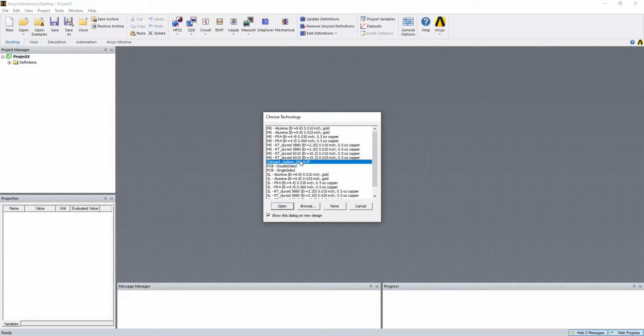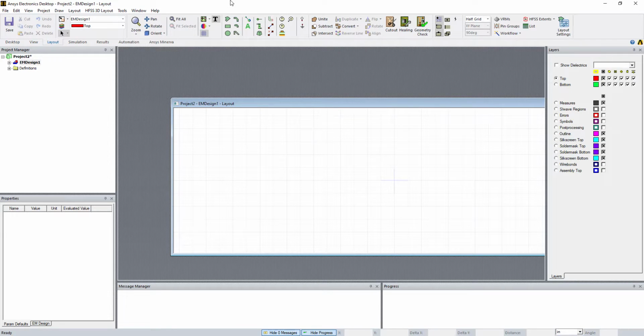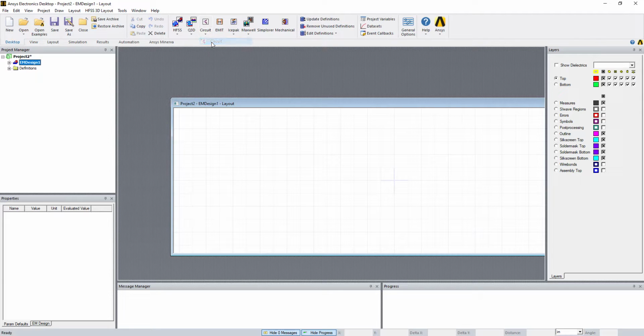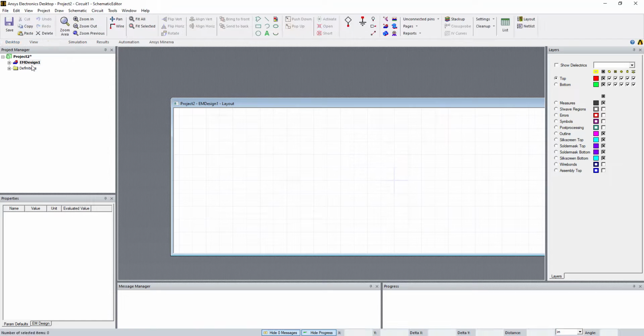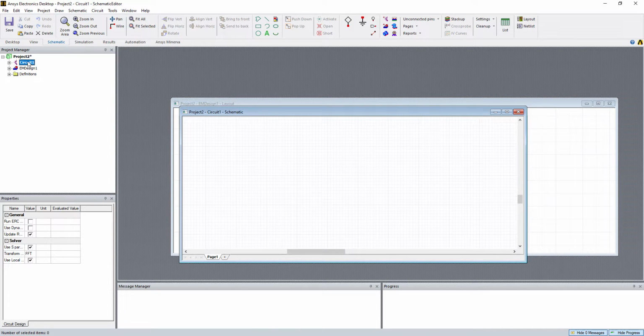And you're going to select the library. Just to let you know, I did update the library, so if you want to, you can download it off the Google Drive. The links are in the YouTube videos. You're going to select that. The reason you need to do this is we're not going to use this, but it loads up the planar via element so that now you can properly use the ground pads. Then from here, you would create your circuit and continue on. So the first thing you're going to do is just load up a blank 3D layout project and then go on to your circuit, okay?